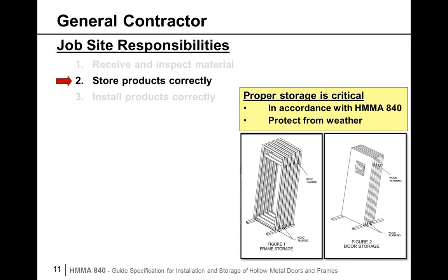Now, the next item that is critical is the storage of the product. And in any of the installation standards, the key is to store the hollow metal, and it also relates to hardware, any building products, in a protected area away from weather.